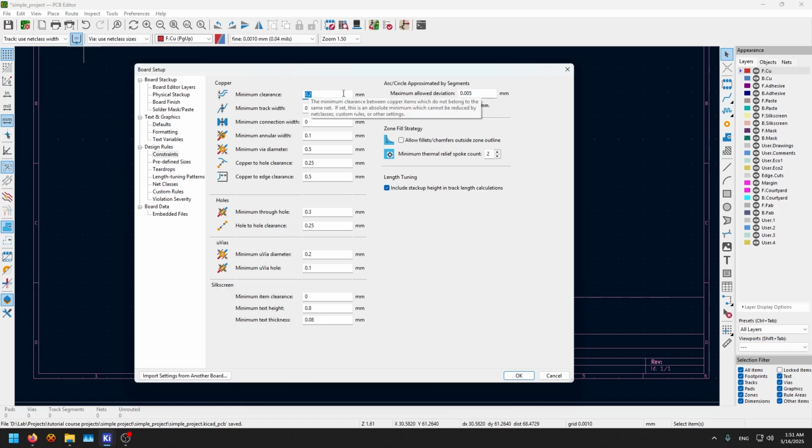Why is this important? Because it's not really funny when you finish the design and you route everything, only then to know that, well, your manufacturer can't do these tolerances. Please redesign all of it again. It's really not a fun thing to do. So basically, make sure you go to your manufacturer capabilities page, understand them very very clearly, and basically just put them in here.